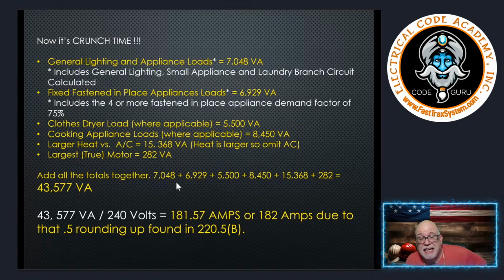So you take 83% of that, and the conductor cannot be smaller than 83% of the rating. Now, if you have adjustments or corrections, you've got to account for that, and it might cause you to go to a bigger size conductor, because after those adjustments and corrections, you still can't have a conductor that's less than what? 83% of the rating of the service or feeder.